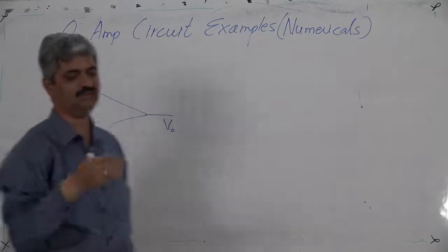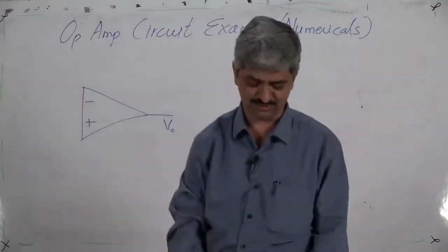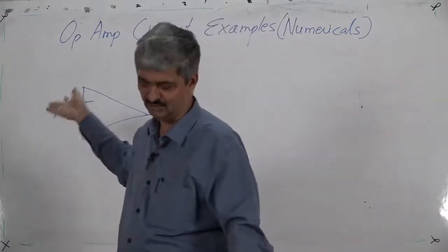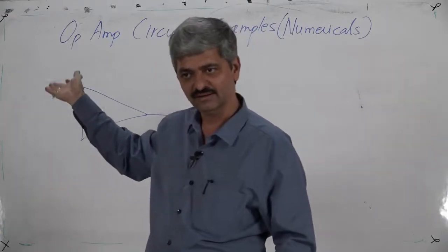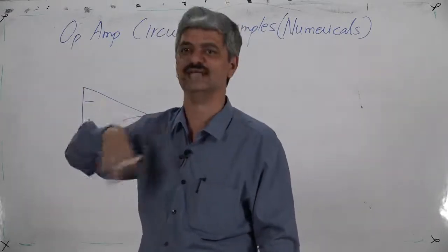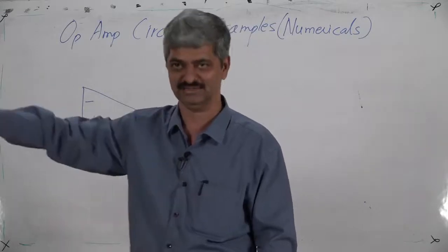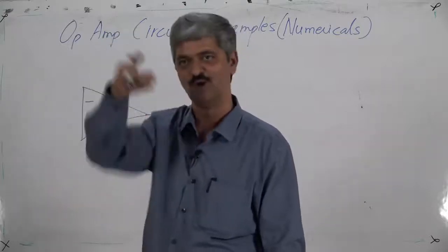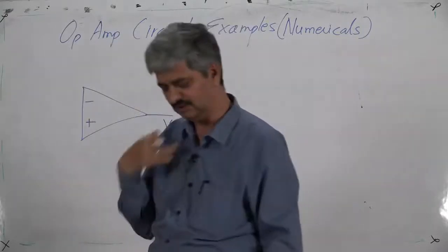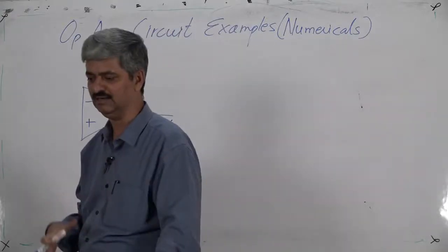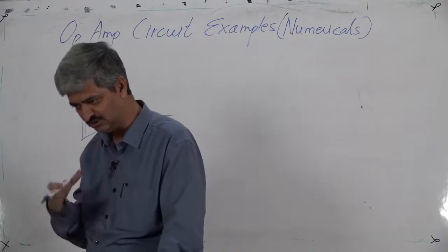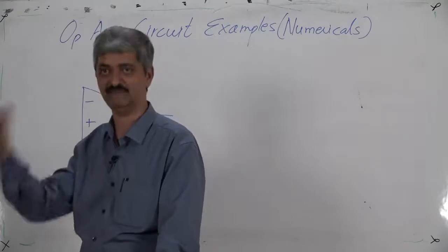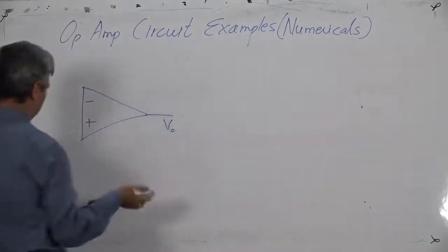All resistances we take would be in kilo ohms, so that, since it is a ratio, while calculating currents we can take it to be as good as ohms, because it is going to cancel everywhere. So currents would be in milliamperes in that case, and they would be equal. Each time there is no need to write upon 1000, upon 5000; you can write upon 1, upon 5. The unit for voltage is volts, the unit for resistance is kilo ohms, which gives the unit for current in milliamperes. That will reduce the calculation burden.